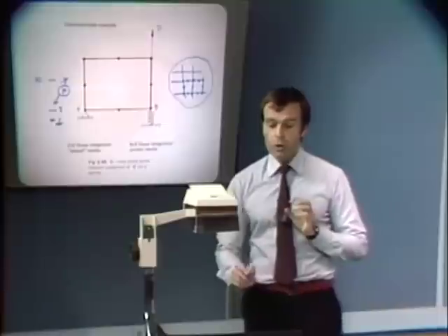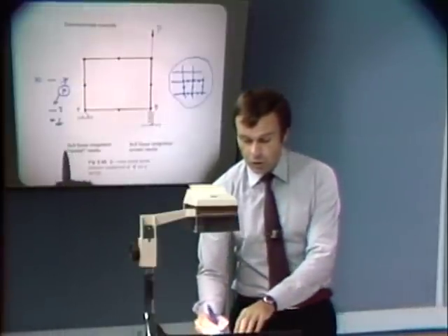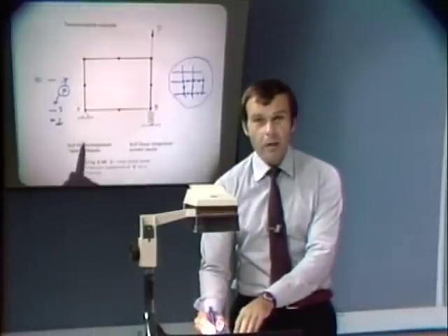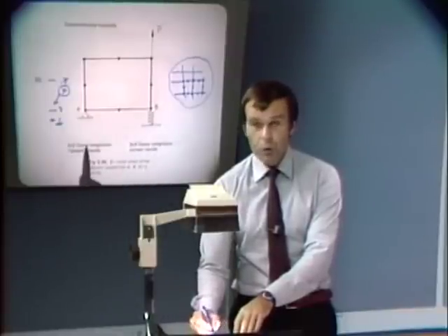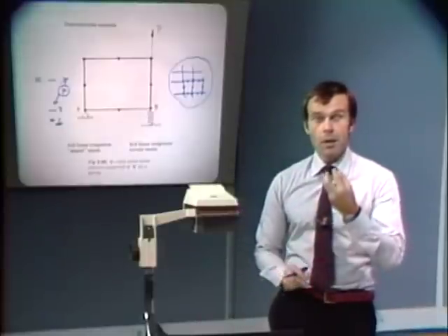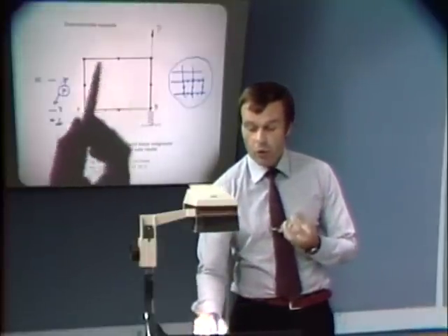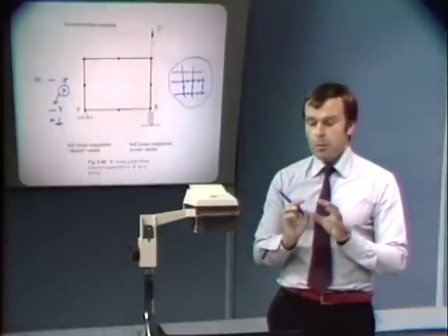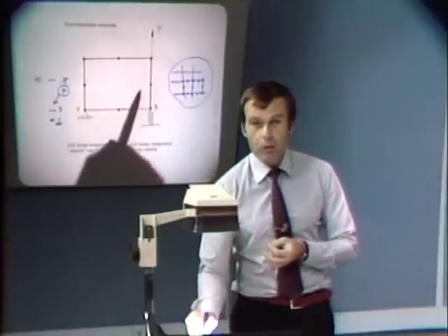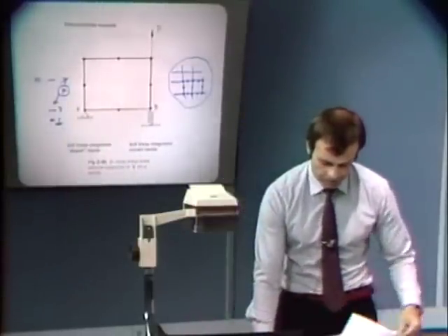However, if you do use reduced integration, we call this reduced integration because we are not evaluating the stiffness matrix exactly, you should be aware of the fact that for a single element or for certain element mesh layouts, we can run into numerical difficulties.